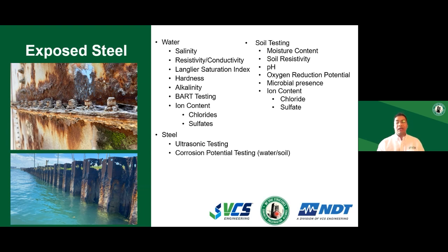It does not mean that if you have fresh water that you won't have any corrosion. You still can have severe corrosion in fresh water. Typically, the rates are low, but you run a test called Langelier saturation index, and that can tell you if your water is corrosive or not. And this test is typically run for freshwater sources.